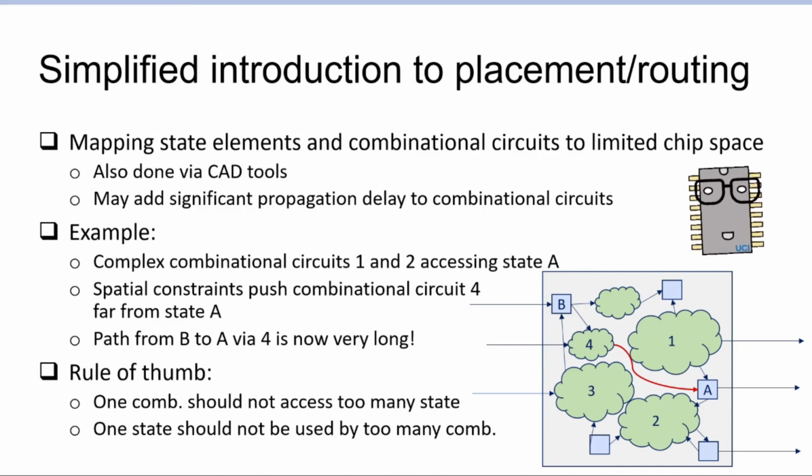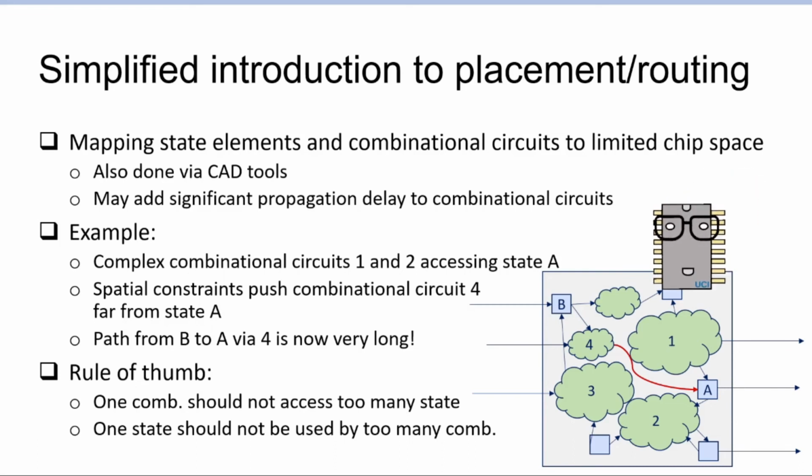Regardless of how shallow your logical representation of the circuit is, regardless of whether it does nothing, if it just has a buffer or anything, the propagation delay for that path is going to be longer than the clock period, because it's just a physical limitation of our universe. Light travels 10 centimeters over the course of a clock cycle. No signal can travel faster than that. Yes, we're going into physics now, which is cool.